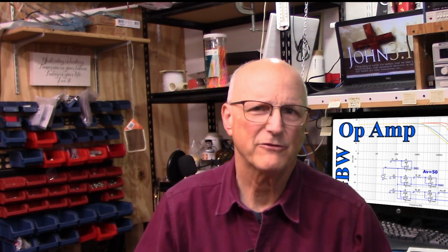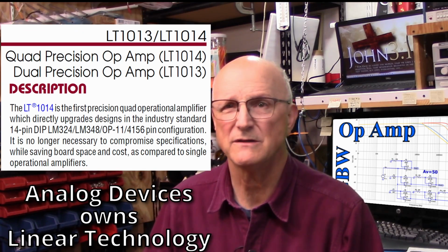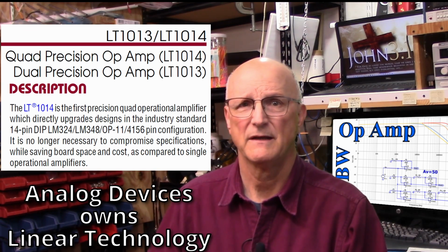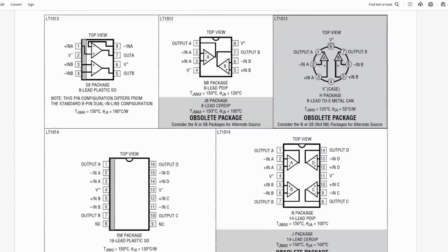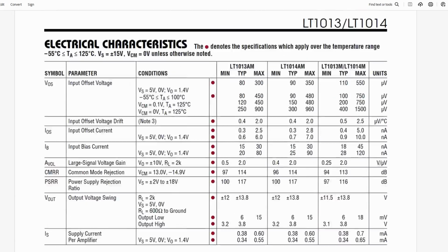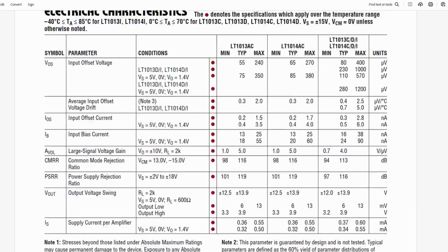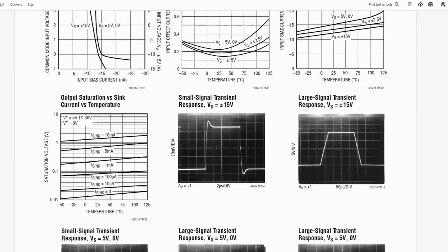So let's see how this affects our amplifier design. Suppose that I'm using an Analog Devices LT1014 op-amp. I look through their data sheet to discover, well, they don't give a gain bandwidth product specification anywhere in their tables. So what do I do now? I start looking for a graph of some sort which will reveal this to me.